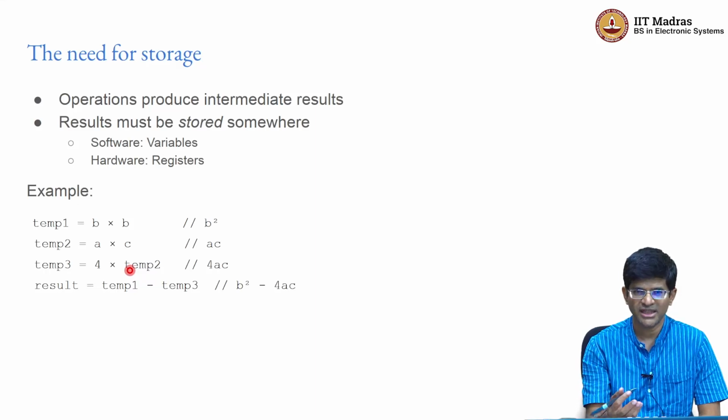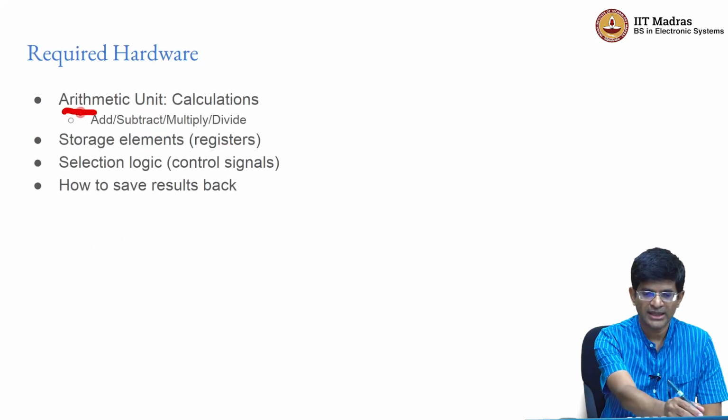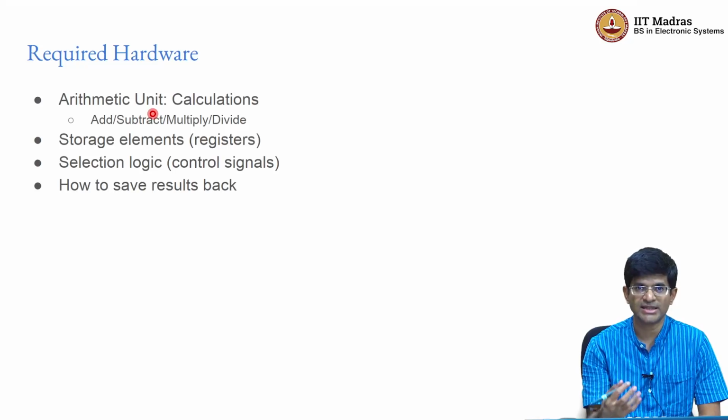But intuitively, hopefully this is not too hard to understand. The basic thing I'm trying to say is you could potentially just create 3 multipliers to perform these 3 computations. The alternative is to have one arithmetic unit and see whether I can give it the right inputs at the right times in order to perform all the computations that it needs.